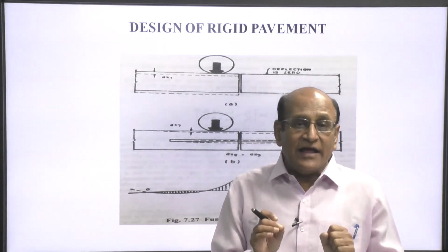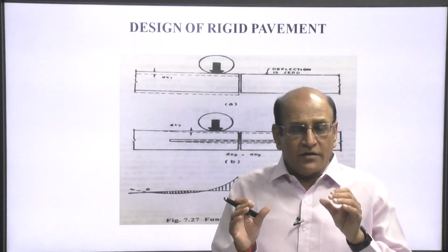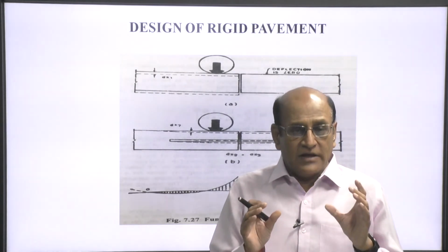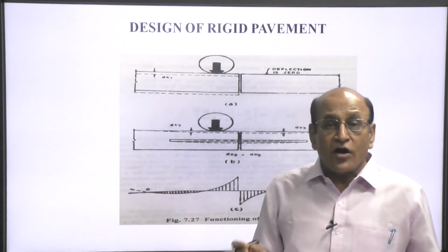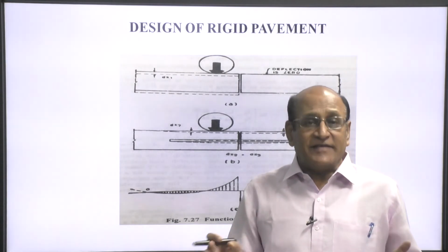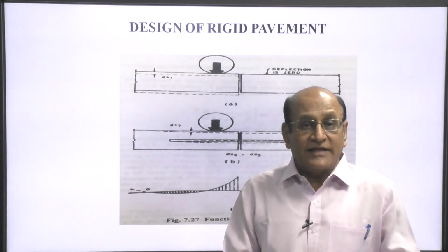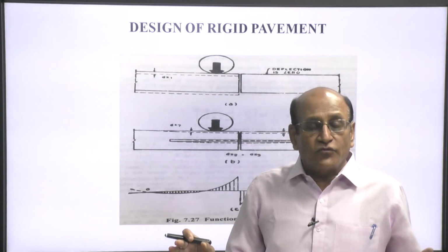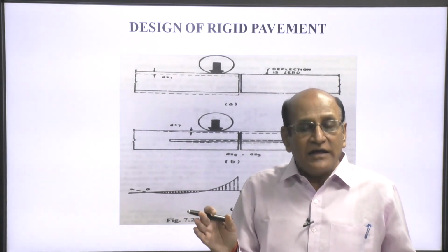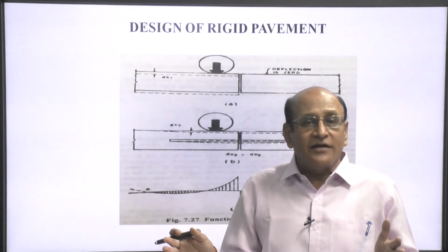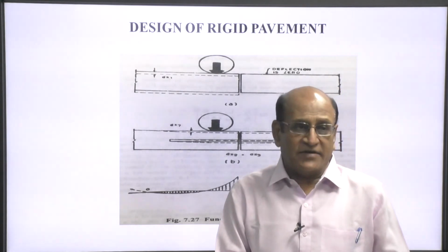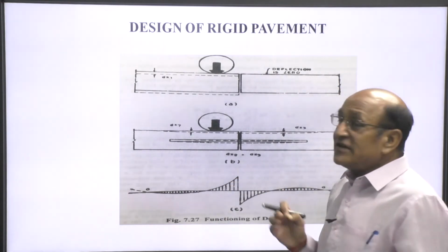So, it is kept in a hard cylindrical shaped material. At the end a cotton pad is placed. So, when temperature rises, there will be expansion, so the dowel bar will move inside and adjust to the length of the slab, increment or decrement. This is the one thing.